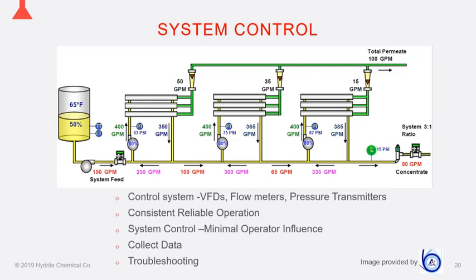But what you can see here now is how you go from loop 1, which we looked at already: 150 gallons per minute of feed, joining the recirculated 250 gallons a minute to make our 400 gallons a minute. And you can see that there's 50 gallons a minute of permeate coming through. At that point, we've got the 7.5% solids and 100 gallons feeding loop 2. So loop 2 is now seeing 7.5% solids, and we've got 100 gallons a minute feeding it.